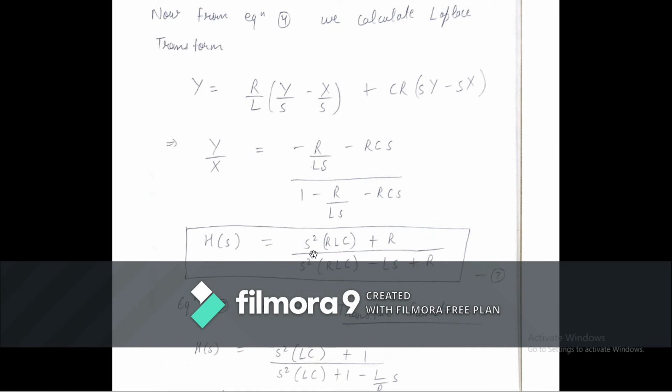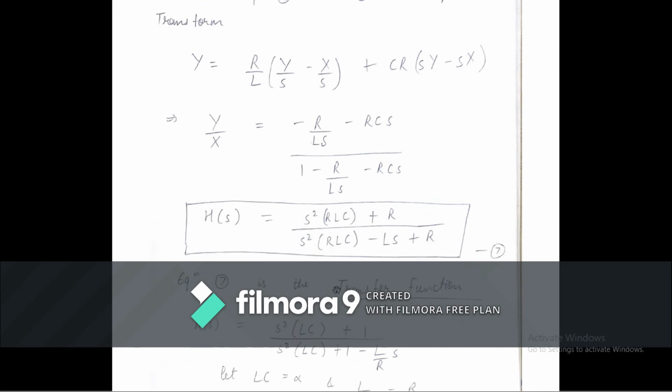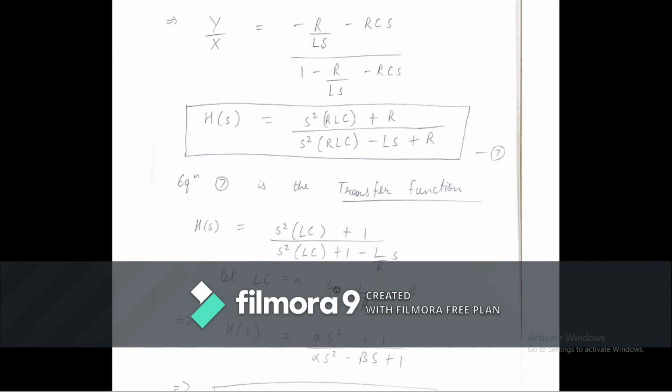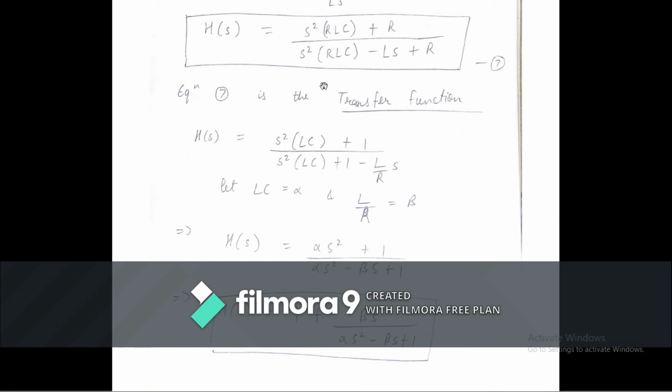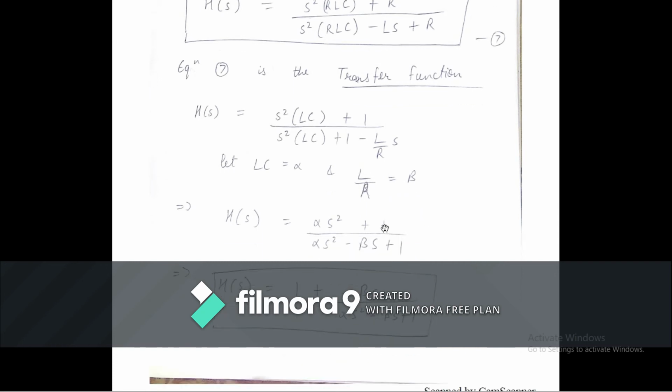Now we have to find its zeros and poles, and also its region of convergence. So we will further simplify this equation. We have taken R common, and we have put LC equal to alpha and L by R equal to beta, and we have added plus 1 and minus 1, and simplified our transfer function as this.